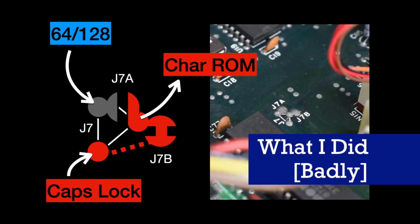Okay, so the first thing I managed to do successfully was cut J7B, and I actually did this by heating it with the soldering iron and then using the solder sucker to remove the blob there, and that correctly disconnected the caps lock key from the character ROM. But then when I was trying to solder J7A, I managed to remove the right hand side of it because it's just a thin trace on the board and it just peeled away.